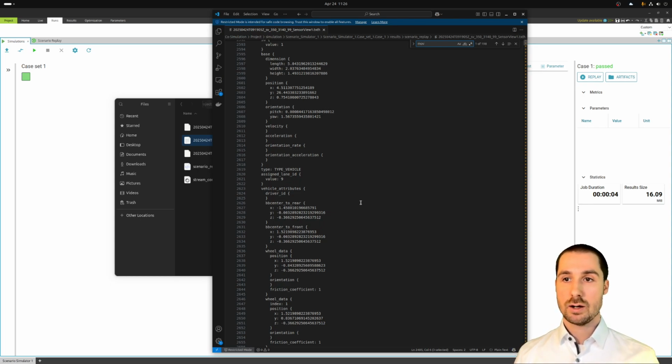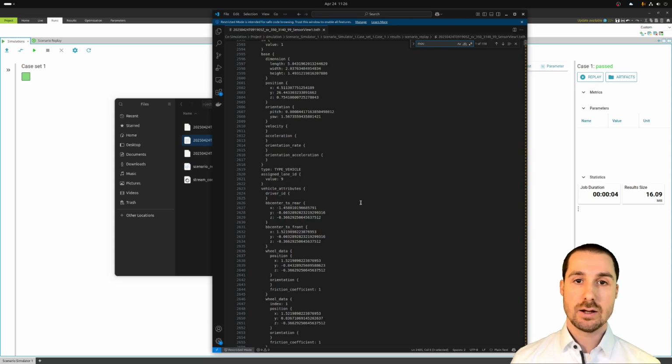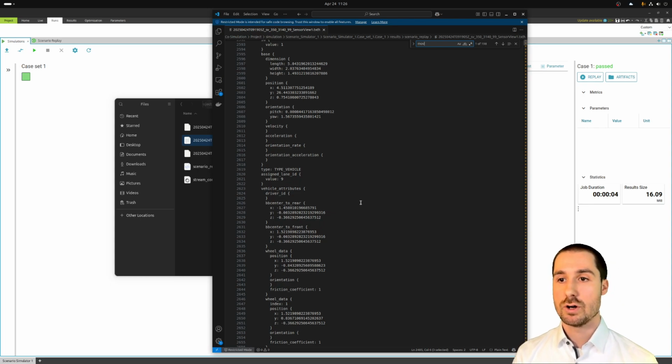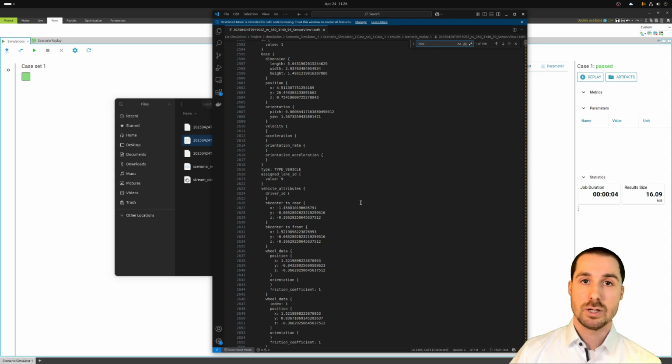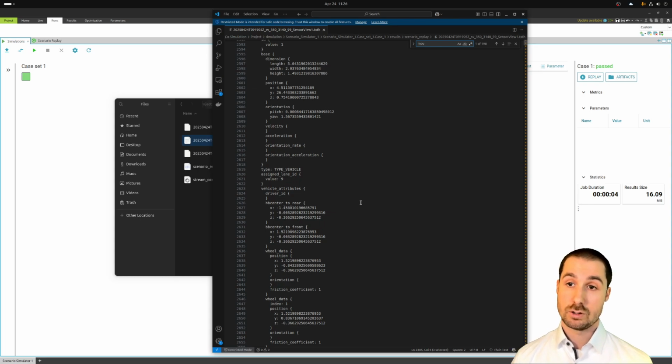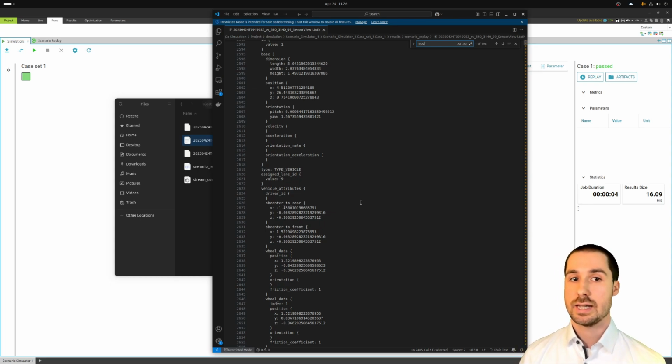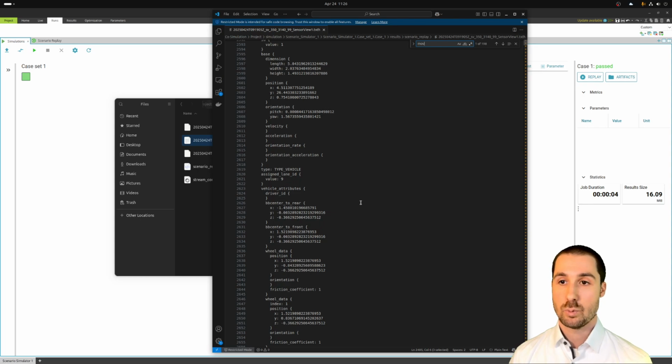This way you can replay exactly the same scenario, exactly the same environment simulation, over and over again in a sensor model during development, for example, or for validation. You don't need an environment simulation to validate a sensor model. You can simply use OSI trace files and feed exactly the same data into the model over and over again. That's a major benefit of this standardized interface and also the standardized file format we have here. That's it about the trace file format.